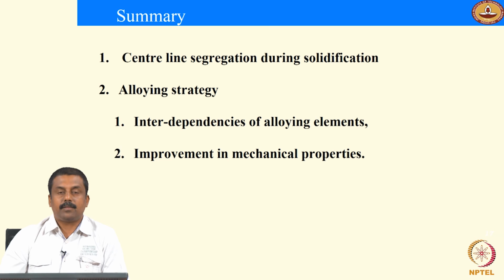Subsequently, delta ferrite can transform to austenite, and this can lead to a segregation of carbon in liquid. And so when you have peritectic reactions, obviously you may also have austenite forming from liquid plus delta ferrite mixture, and you may also locally change the carbon concentration of liquid because of this reaction.